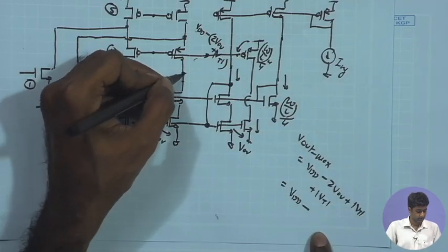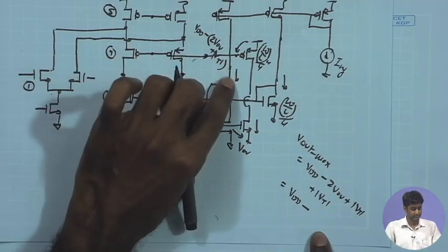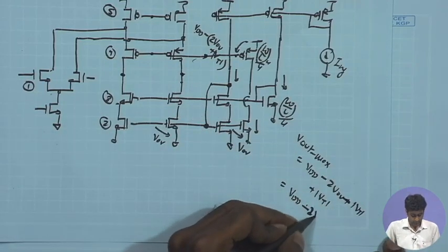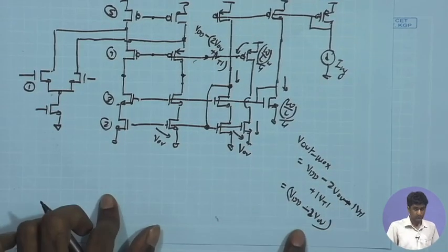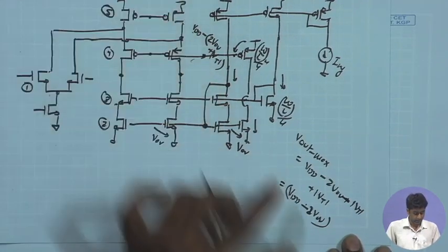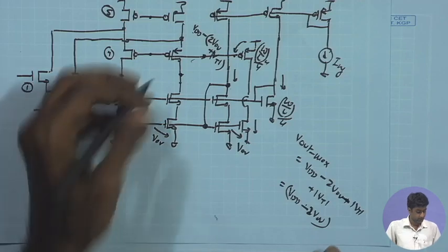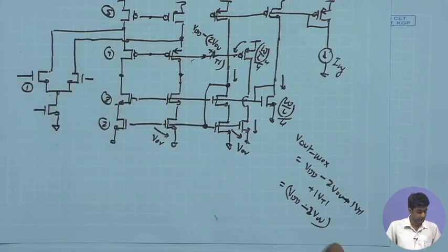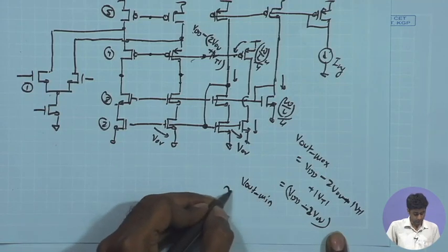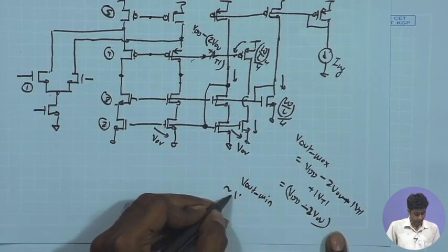As a result, the maximum potential that you can have over here is plus this plus mod Vt, sorry. So, you have a minus sign here, so minus 2 V overdrive. So, this is what we expect, and as a result, once again on the upper side I have the V out max, which is VDD minus 2 V overdrive, and on the lower side we have ensured that V out min is also going to be 2 V overdrive.